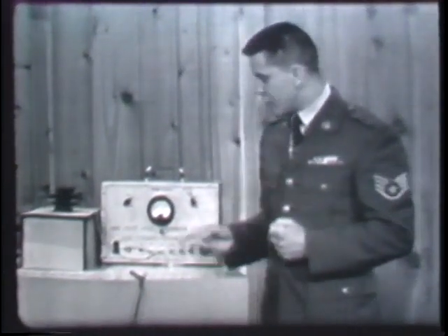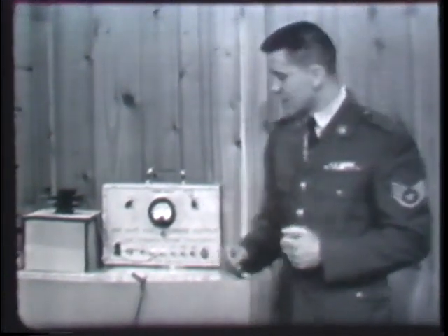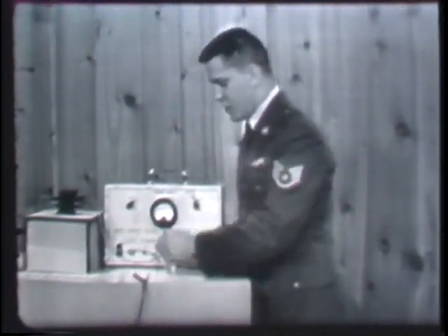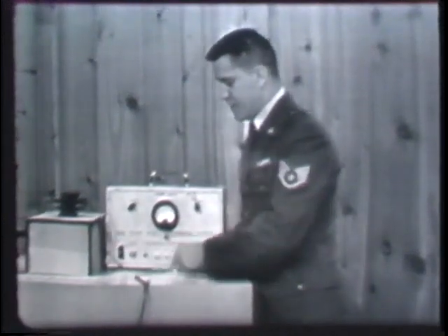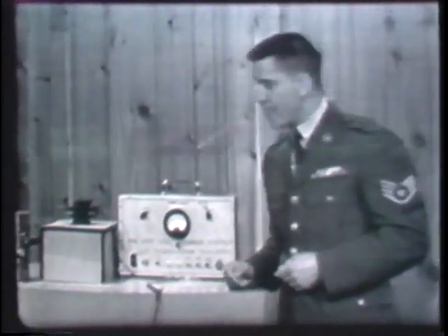Well, let's measure the resistance of the windings in the transformer we're using here and see if this holds true. Before we do it, however, there's a few words of caution I should point out: whenever making resistance checks in a transformer, ensure there is no voltage applied to the transformer. So let's turn the voltage off, disconnect the lead so we'll get accurate readings on our transformer windings, and let's proceed with the checks.